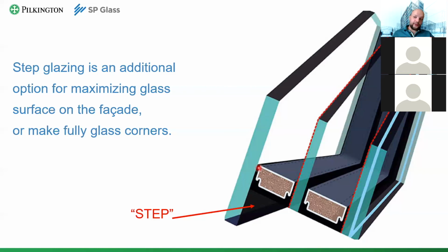Now what I forgot to mention is that primary and secondary sealant can be gray in color upon request, but this solution is rarely used because it implies additional costs. And also grayish color can differ on the facade. But okay, who am I to discuss the design preferences here? Okay, the usual one is black, of course.